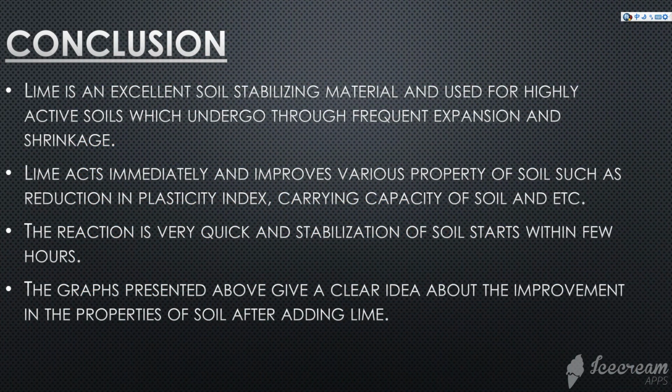My name is Young Divo, and I will present the conclusion. In conclusion, lime is an excellent soil stabilization material used for highly active soil which undergoes volume expansion and shrinkage. Besides, lime acts immediately and improves various properties of soil such as reduction in plasticity index, carrying capacity of soil, and so on. Then, the reaction is very quick and stabilization of soil starts within a few hours.